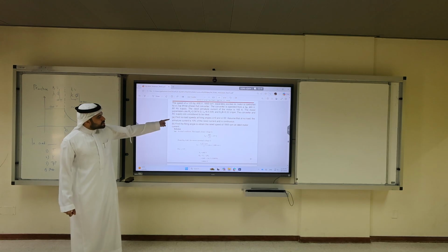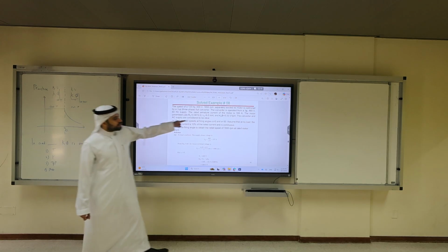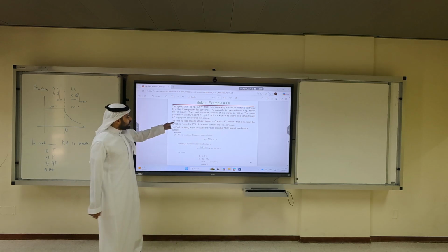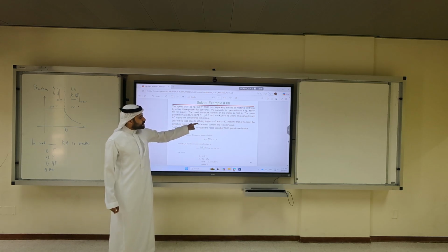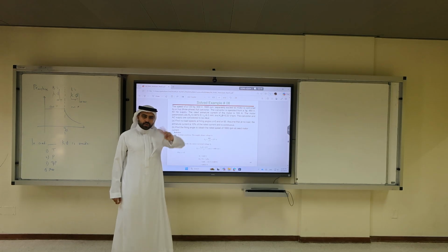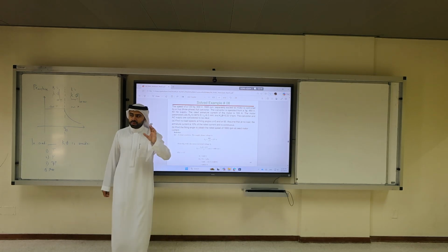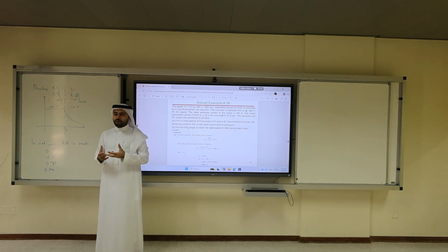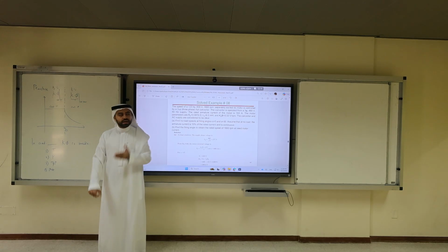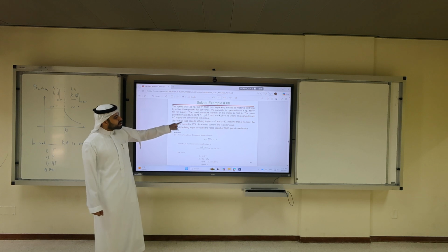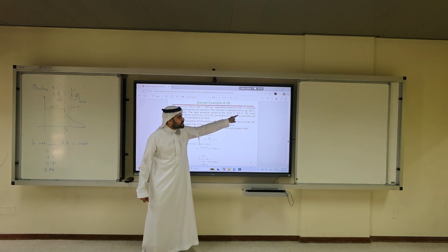The question is, he gave you the parameter, he gave you K flux in voltage over RPM. He said find the no load speed at firing angle alpha 0, alpha 30. Assume at no load IA is small, which refers to rotational losses. He said at no load the IA is 10% of the rated current. What's the rated current? 165. So what's 10%?